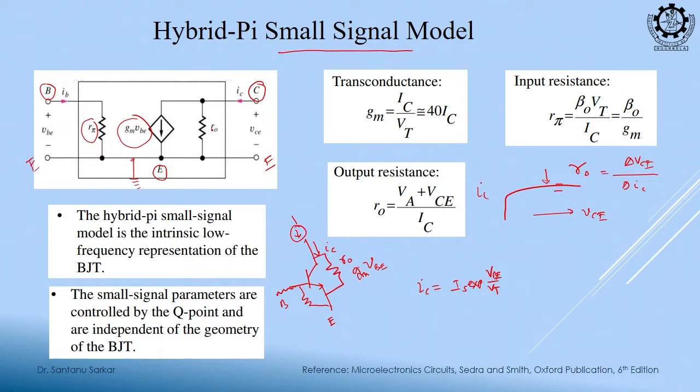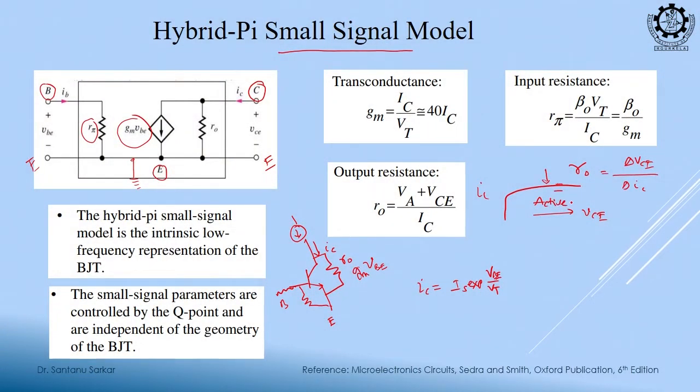So, do not get confused that there is a resistor; this is a model. We are modeling the behavior of the BJT characteristics, because the current is flat in which region? Active region, right. This flat current is like a constant current source, which irrespective of my voltage should provide me a constant current, is it not? If I have a constant current source, my load voltage may vary, but the current should not vary. You see, in this region this is the same nature. So, this I can model with a current source. What is the model of a current source?